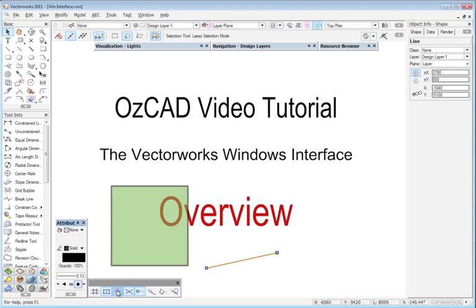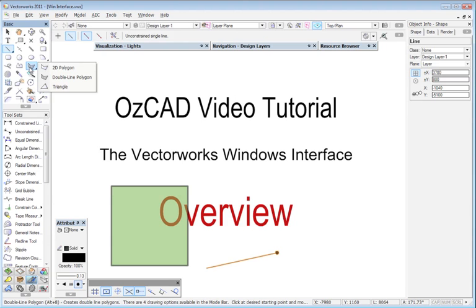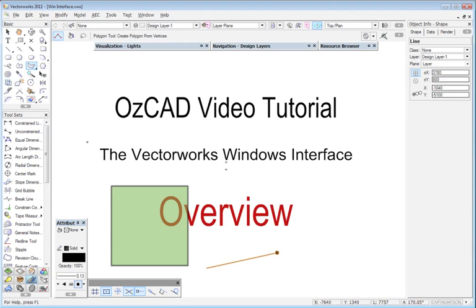These other four are generally on, although some people like to have the snap to angle turned off, and having that turned off will mean that if you take, say, the polygon tool, that as you start to draw, this line won't be constrained in any way, but you can make it become constrained by pressing the shift key down, and if I hold the shift key down, then I will get a constraint kicking in.